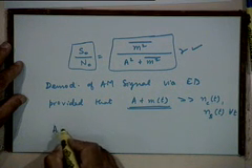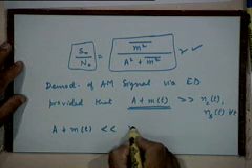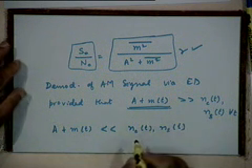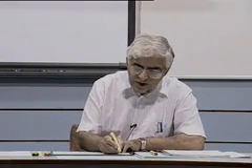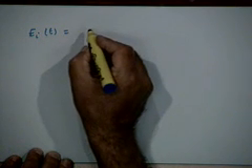The performance is identical. Then we considered the other extreme, when noise takes over, that is, when the opposite is true, when A plus m(t) is much less than these two things, that is, the signal is much weaker than the noise, right, and under this condition we have obtained an expression for the envelope of the output signal. Let me just recap how we obtained this expression.